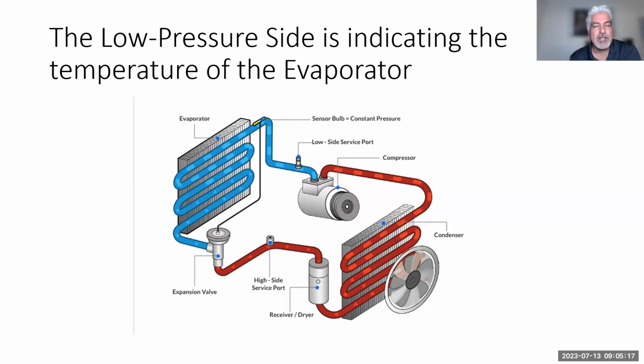So when guys do modifications, and I don't know why, I'm on the PowerStroke 6.0 forums, and the guys want to put electric fans on there, when I think the viscous fan clutch that comes from the factory works just great because it's on my truck, I know. So what I'm trying to say is airflow is critical. Is that fan turning on when they turn on the air conditioning? Because again, you need to have a hellacious amount of airflow going across there. And then it manages itself because as the vehicle's going down the road, we don't want that fan kicking on as much, because the ram air is supplying that air as you're going, let's say, 70 miles an hour down the highway. But again, what I need you to understand is airflow, and having a clean condenser with no obstructions in the front of an air conditioning system.